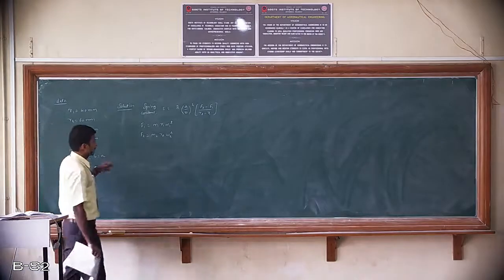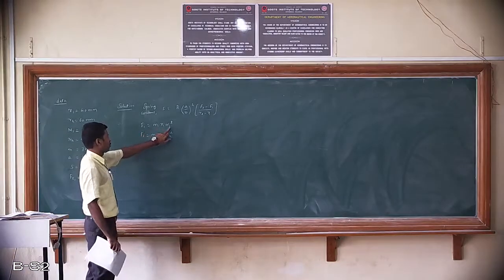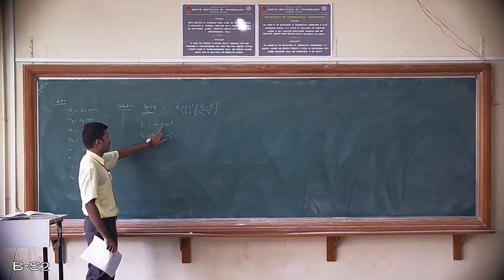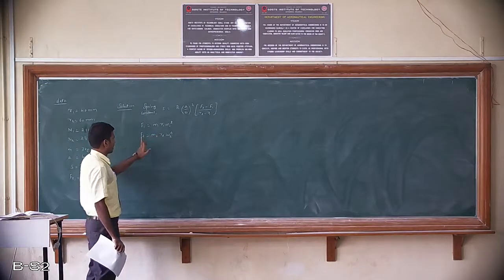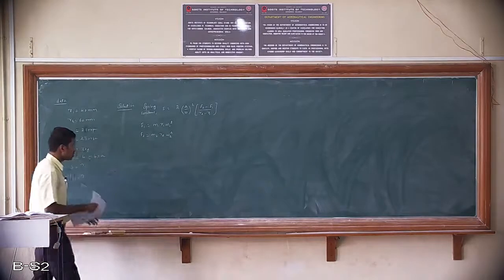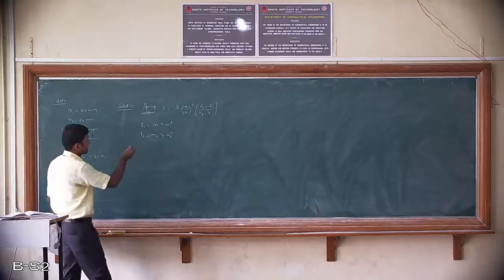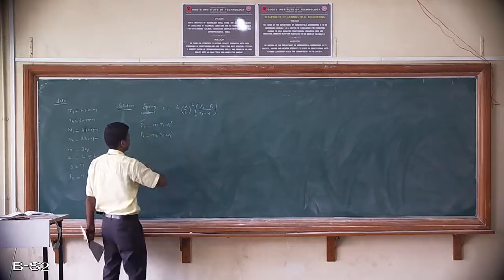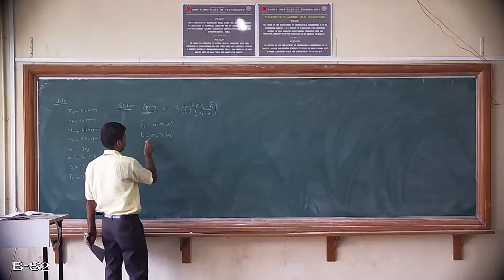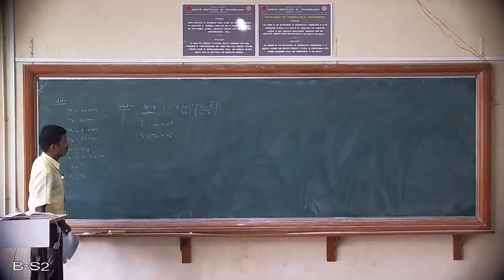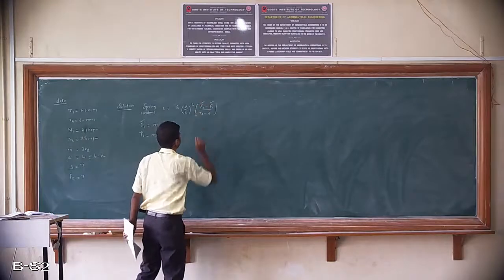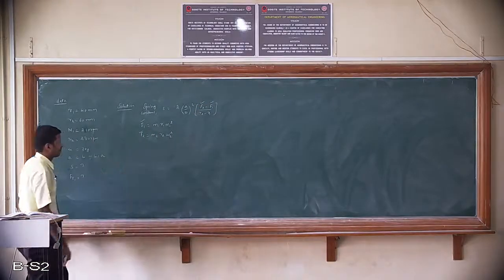So this centrifugal force can be obtained by m r omega square. As it is F1, I am marking it as M1 R1 omega 1 square, and F2 is equal to M2 R2 omega 2 square. So this is the equation. By this equation I can get the value of F1 and substitute it here, and to get the value of F2, this is the equation, M2 R2 into omega 2 square, so that I can get the value of F2 and substitute it into our governing equations.